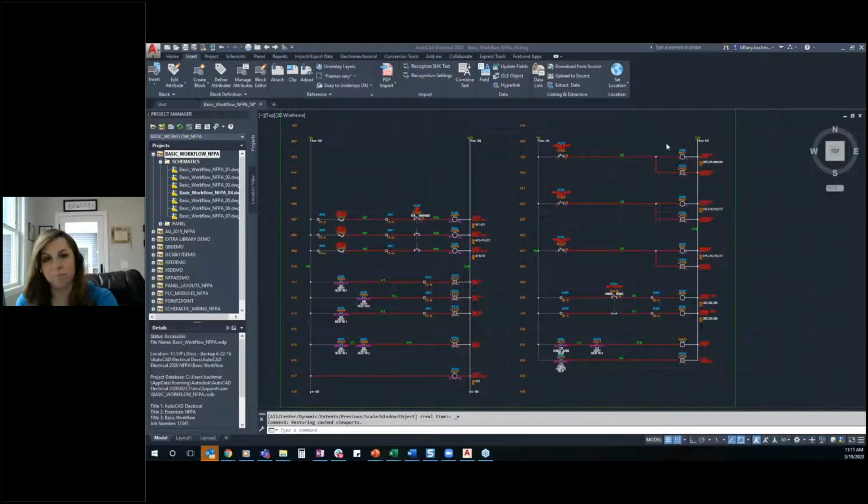So there is a connection between that block and Vault, and this is how it's dynamically adding rows to that block, or that table, I should say, within the block. So if you run the command VLTREVBLOCK, and I'll actually provide a link to this, a video showing how to do this, you'll actually get into that block and you can edit that.